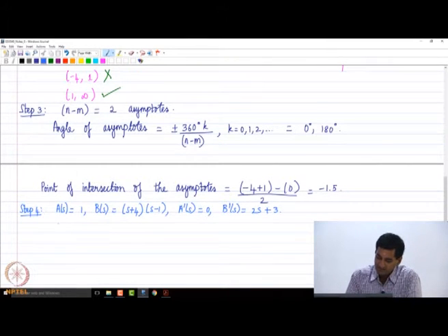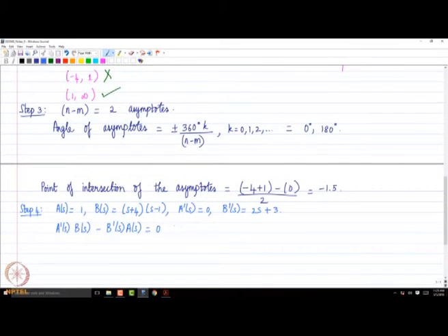If we process the equation A prime(s) B(s) minus B prime(s) A(s), where prime indicates a derivative with respect to s, please remember that, we get the final simplified equation as this. Once again we get s_B, with subscript B indicating a potential breakaway or break-in point. Once again we get the same solution as before, in negative feedback.